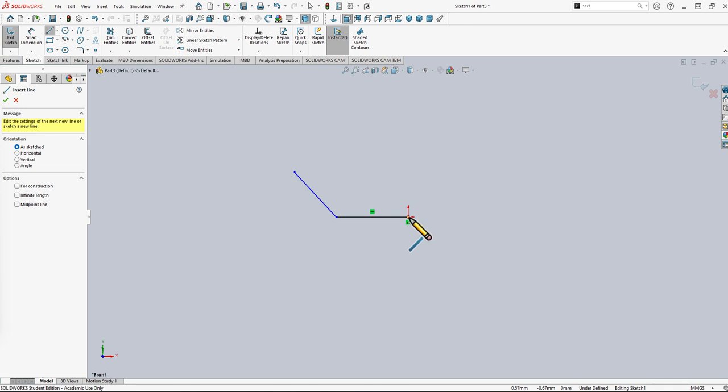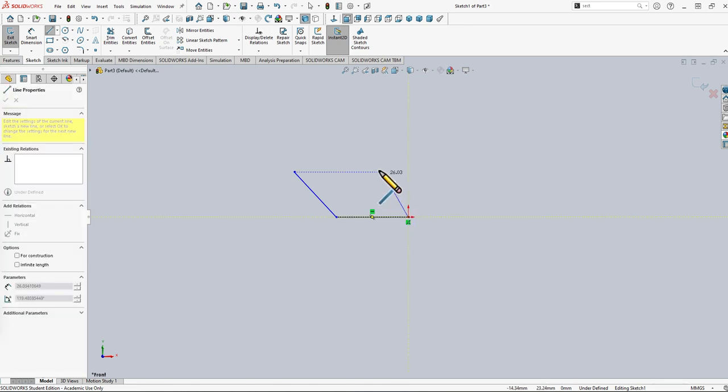And then I'm going to draw the other line that starts at the origin again, and it comes this way. As I'm drawing, SolidWorks starts populating these little yellow lines everywhere because it's trying to make additional sketch relations. So there I can see a little blue line appeared because that is a line that's dropping down that would be perpendicular to that line to the left here. And it just identifies all the different sketch relations along the way as I'm moving in 3D space.